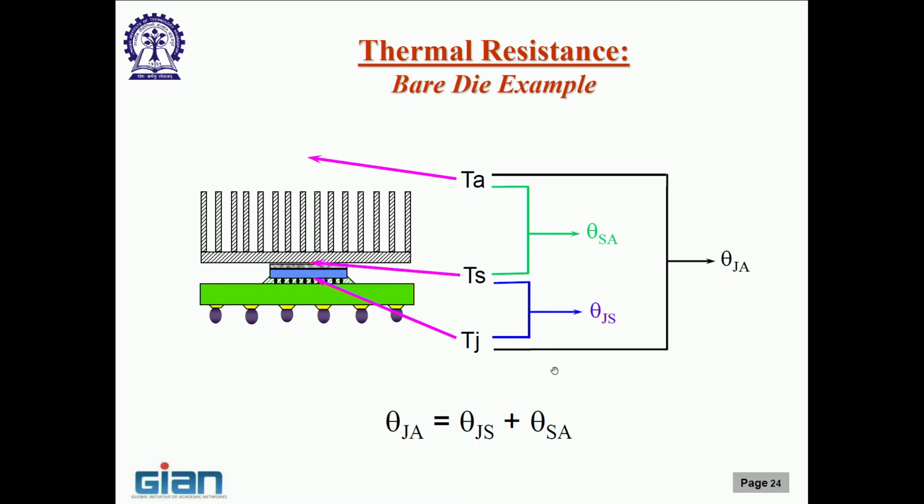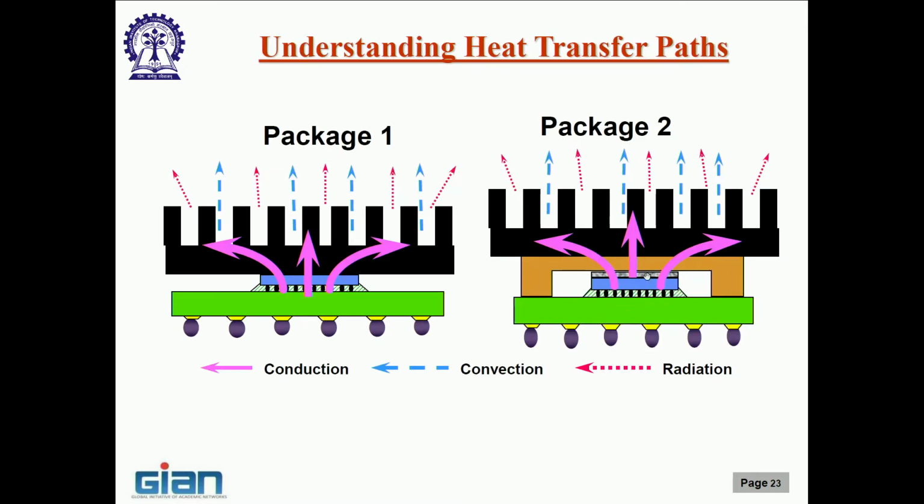Okay. The last note I want to mention is, most of the times, since the processor is sold along with the integrated heat spreader, this interface material typically is solder. Okay. Because solder is of course a very good conductor, this is the back side of the die, so there is no danger of shorting or anything, and typically when your processor goes bad, you just throw this package away. Okay. We normally do not go into this and try to rework this TIM and so on.